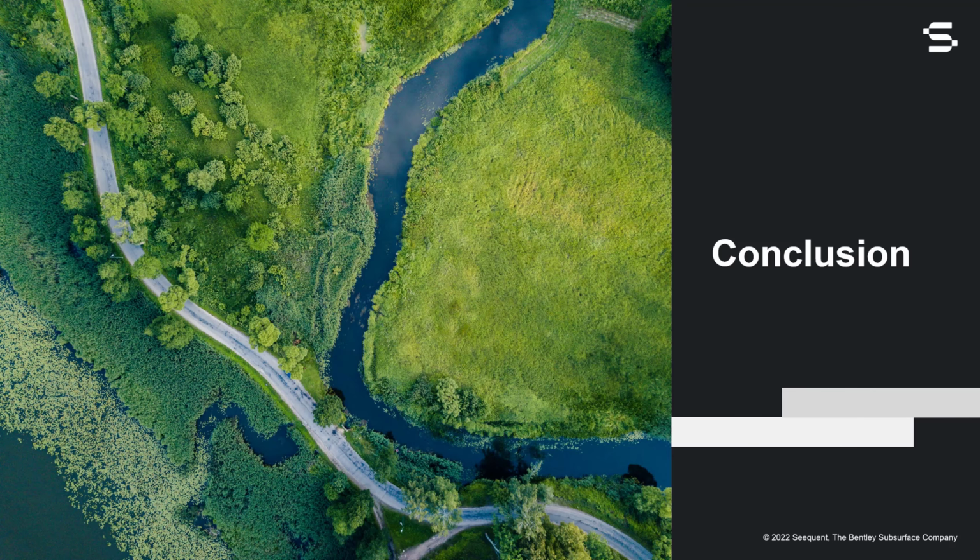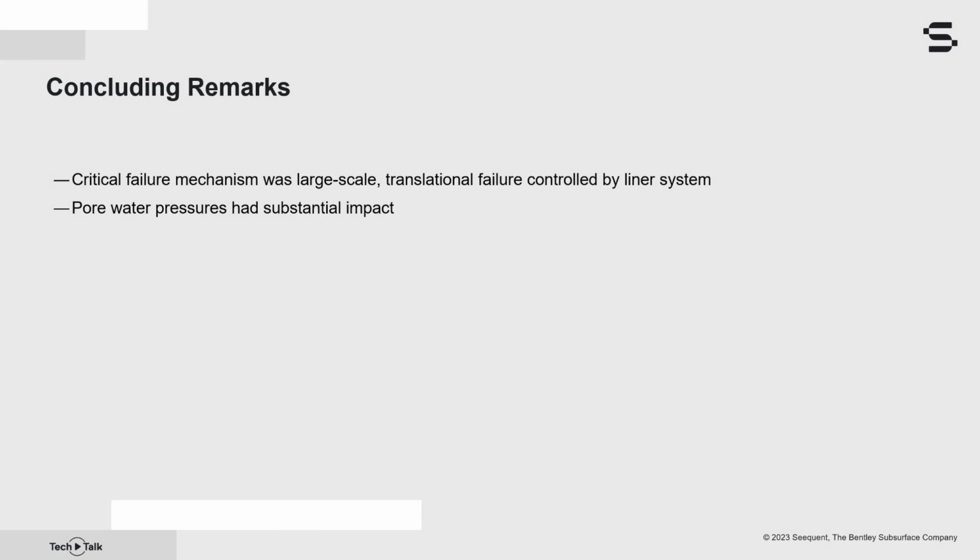This concludes our demonstration of a 3D seepage and stability analysis of a heap leach pad in GeoStudio. Overall, we determined that the critical failure mechanism was large-scale translational failure controlled by the weak surface associated with the liner system. Nevertheless, the pore water pressures had a significant impact on the stability results, with a long-term factor of safety just above 1.2.